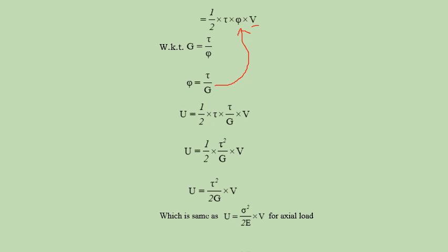So this strain energy is the same form as the strain energy due to axial load, because there we have normal stress sigma and Young's modulus, but in this case we have shear stress and modulus of rigidity.